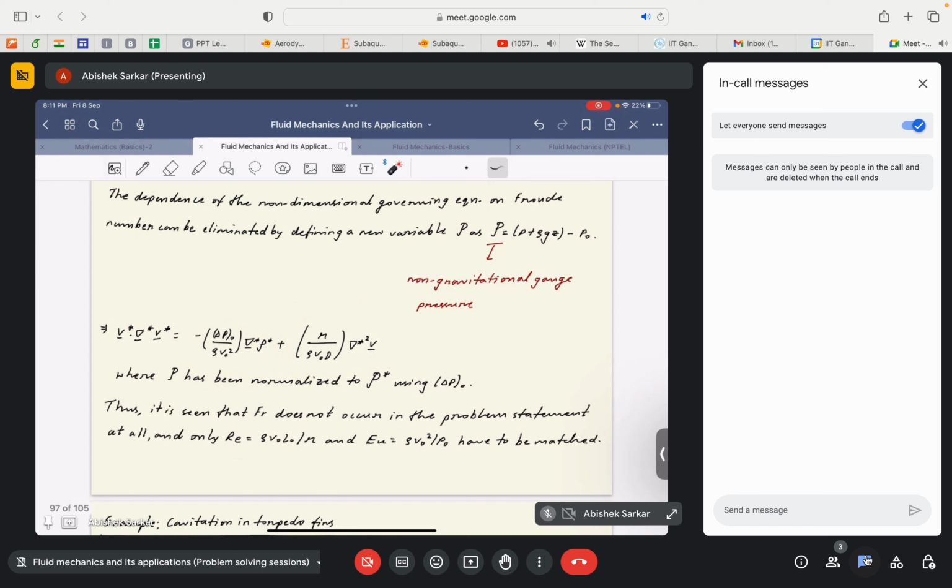in the case of this current flow field, and thus these two driving factors should indeed match each other, so that the equation is satisfied, right? These two terms should match each other so that the dimensionality of the equation is satisfied, because we are not saying that either of these two terms is insignificant. We are saying that both of these terms are significant in the governing equation. So it ideally means that the scaling or the order of magnitude of this non-dimensional number and this non-dimensional number should match, because ideally the order of magnitude of these terms is unity, right?